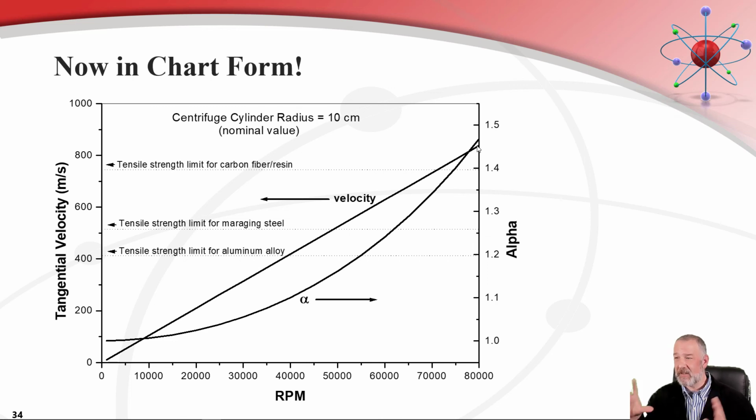And again, this is just an example. This is not indicative of any particular centrifuge technology or centrifuge design. Just something to give you an idea that, first of all, these things are spinning incredibly fast, hence the need for the magnetic bearings. But we can see that RPM, or tangential velocity, directly affects how good our centrifuges are at separating out our uranium into our enriched versus waste streams.